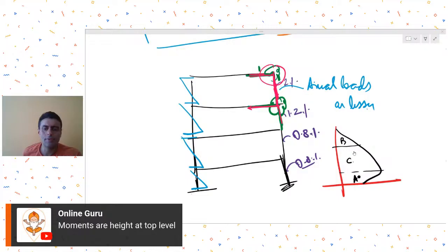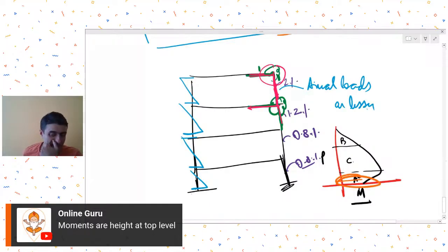Where would you lie in this PM curve of your column at the upper levels? At the upper levels, you would lie in this zone where the axial loads are also lower. Now, when the axial loads are lower and moment is more or less similar or higher on the upper levels, then what happens? You are in this zone.